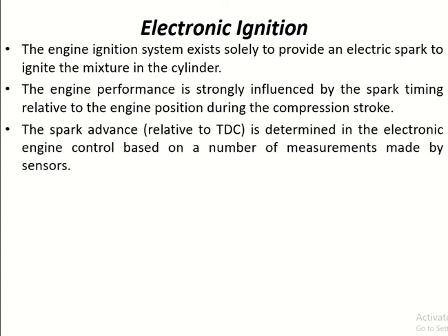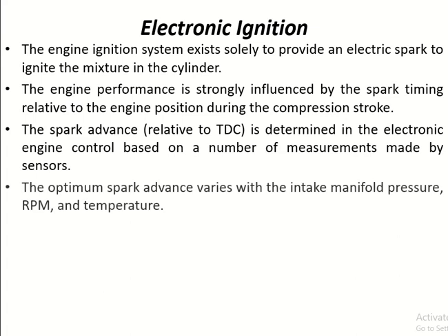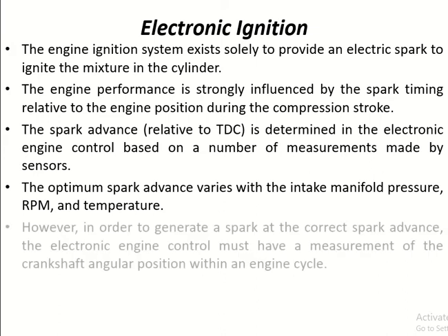The spark advance, that is relative to the top dead center, is determined in the electronic engine control based on a number of measurements made by sensors. The optimum spark advance varies with the intake manifold pressure, RPM, and temperature.